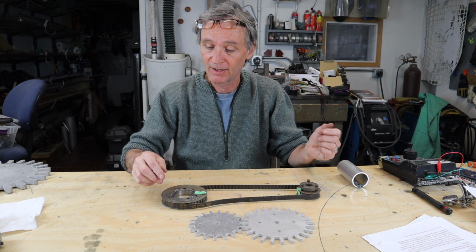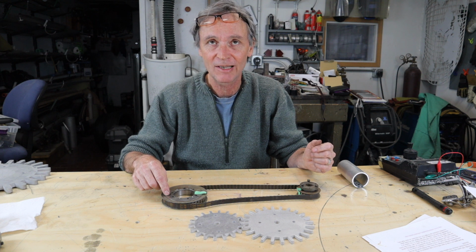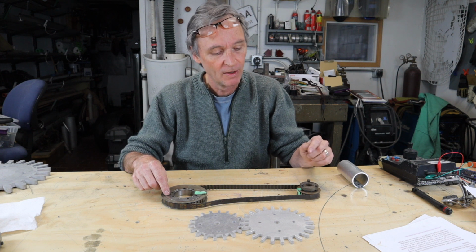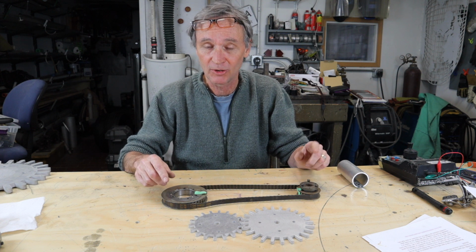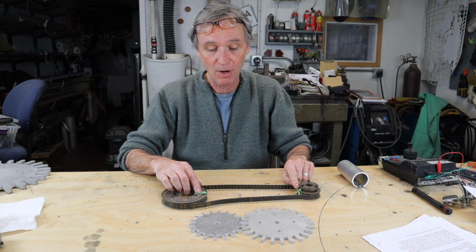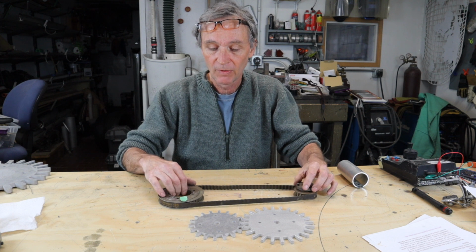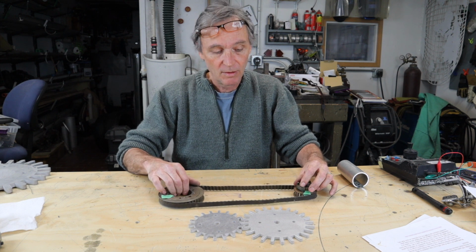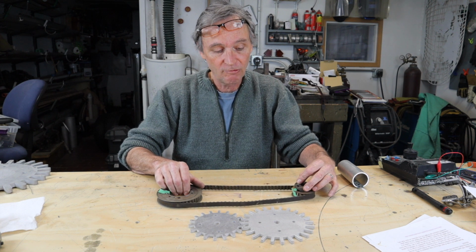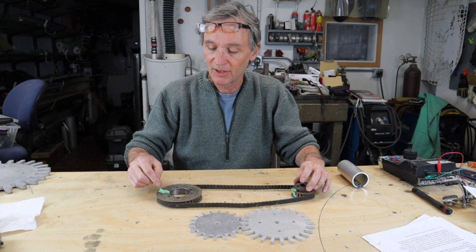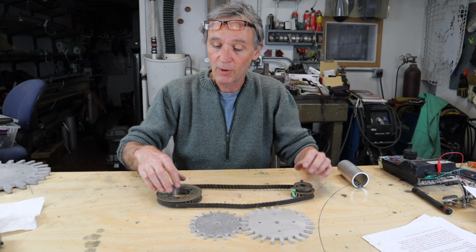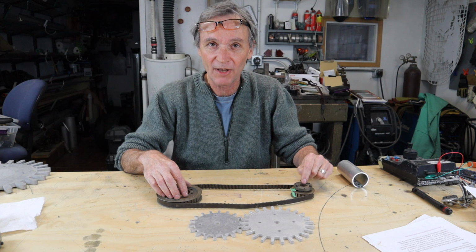So this is a 36 tooth pulley. This is an 18 tooth pulley, so they are a 2 to 1. So again, if our marks are both facing each other, if I drive the large wheel, you'll see that right now this has done a full 360, this has only done 180 degrees. So if we drive this wheel, this goes twice as fast.